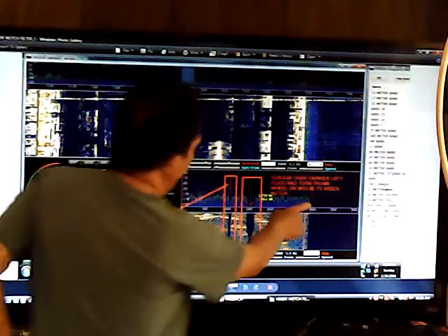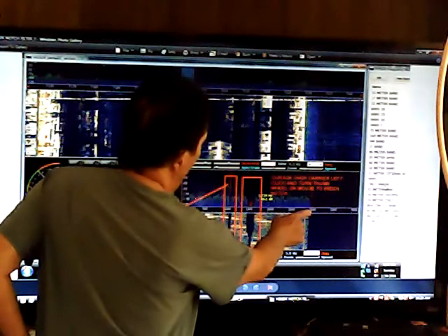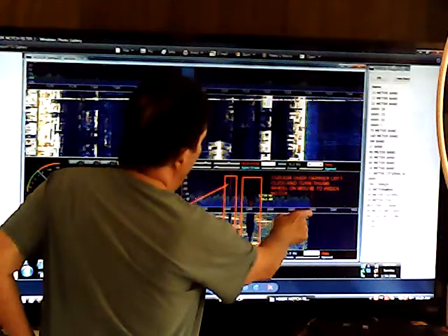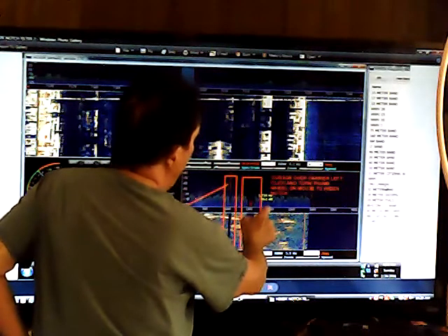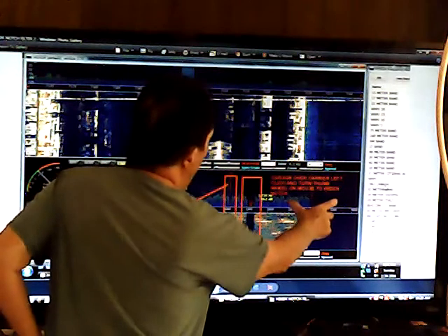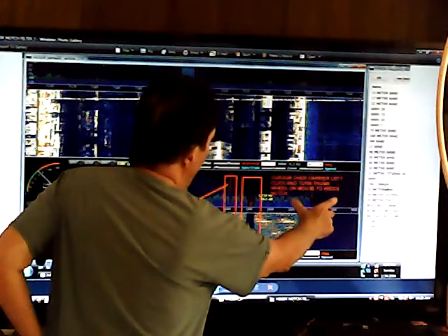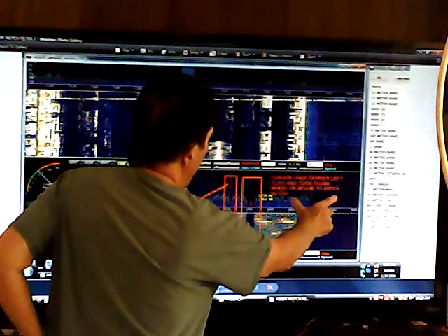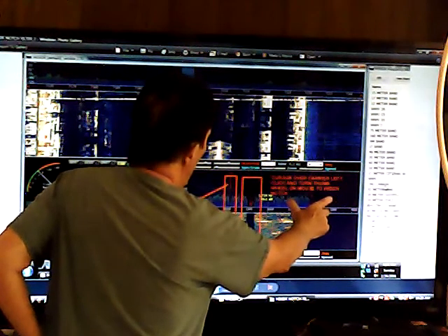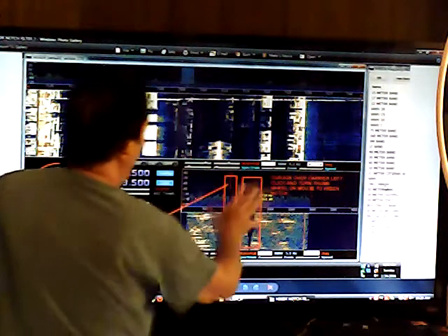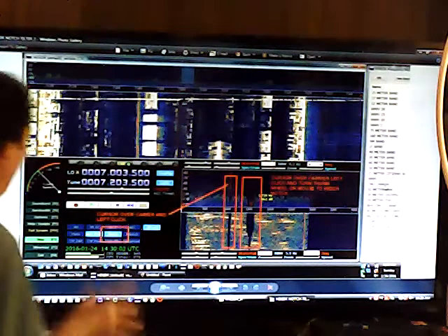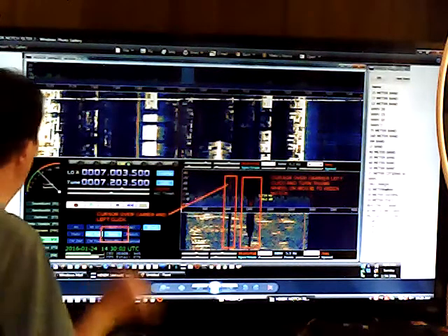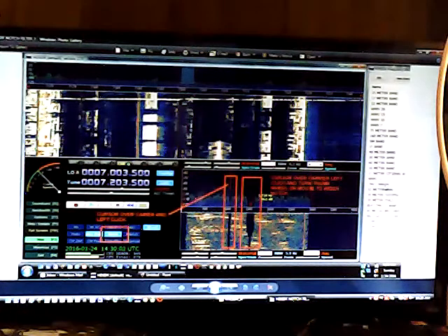You can also adjust the upper bandwidth from 3000 hertz audio response down to, say, 2000 hertz and eliminate an overlapping signal of somebody who is coming in just adjacent to where you are tuned. So those two filter techniques allow you to provide excellent reception with very little interference.